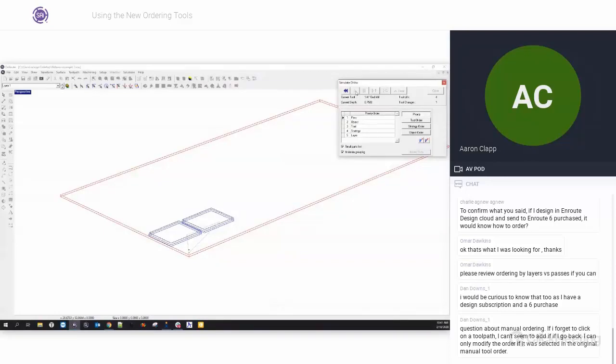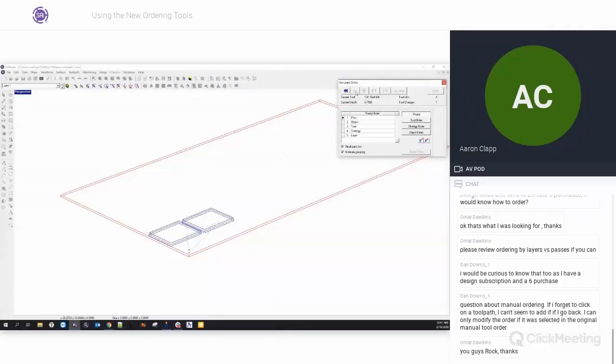What this will allow you to do is have it cut most of the way down on all of your parts, leaving just a tiny little onion skin, and then you could come back and cut it all off at the same time. Or if you prefer it to cut all the passes on a part first, and then do the second pass on all the parts second, and then the third pass on all the parts third, it would do that as well.